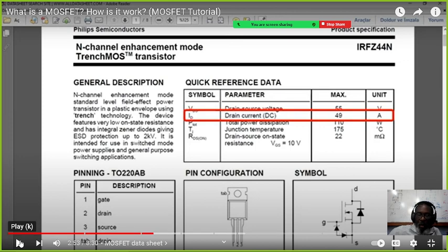And before the class finishes, I'm going to show you how to test it with the tester. Roger and Tracy did it last year. They tested it using the tester and they shorted it out with their finger. You can use a finger to short out the gate and the drain, and then you apply a current to it, and you can turn it on. So they used the tester to turn it on. There's a voltage from the tester itself to turn it on, and I realized it works.